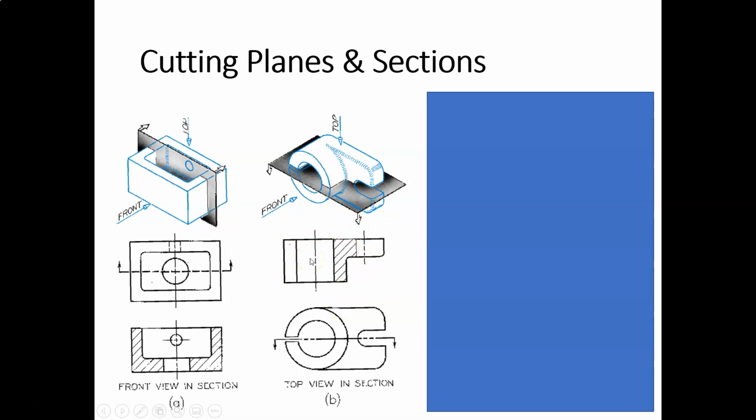Or the other way we can look at it, where you want or need your section view, that's going to determine where your cutting plane line is. You will notice here that this is not an error. The section lines are omitted right here, and the reason why is because if you look closely, you can see right in there, there is a gap in the object.